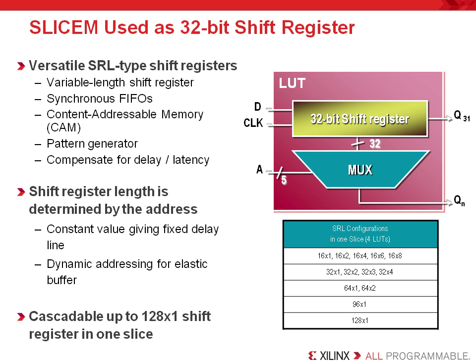So the benefit of using the shift register LUT is that it can effectively provide the work of 32 registers for a pipelined application within a single lookup table. So in pipeline applications, this is a huge savings and perfectly applicable when using the shift register LUT to pipeline your application.